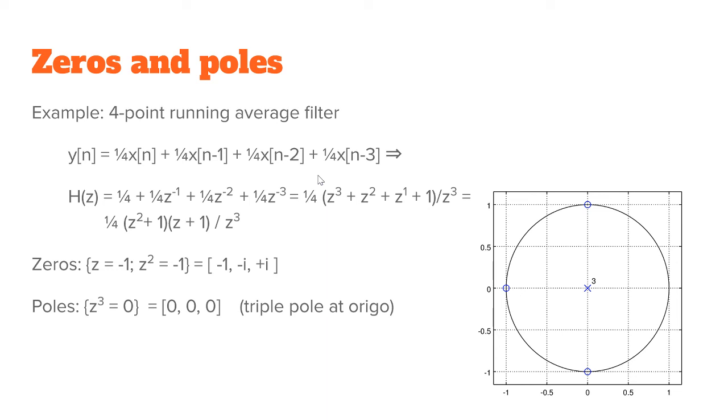And where did we need complex numbers in the analog world? Basically, it's about the phase angle. Without the complex angles, you cannot uniquely define the phase shift at all. So we are just using complex numbers as tools. Same thing here.